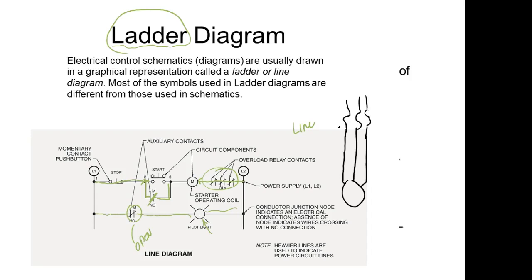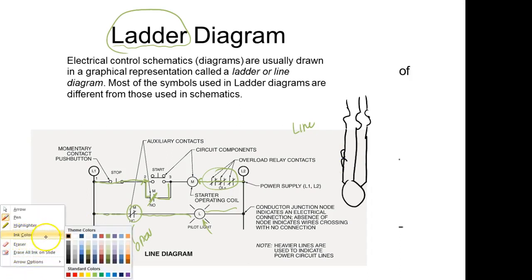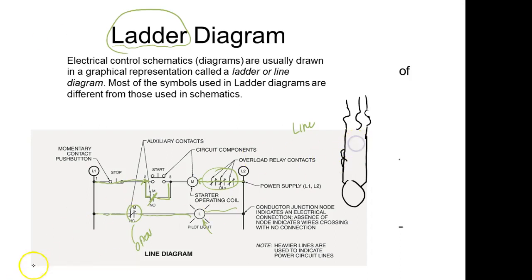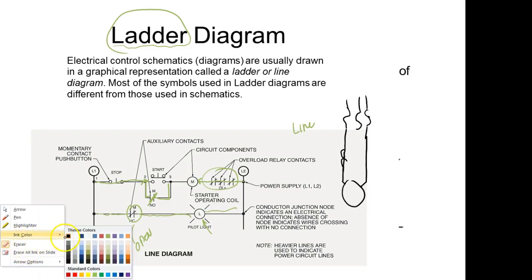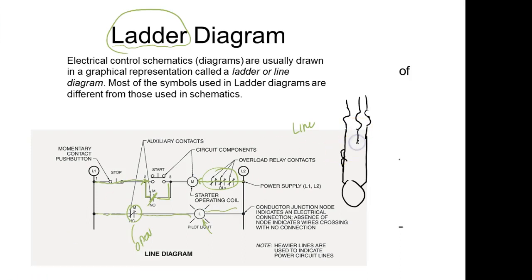So what that means, we need to come up with some method where we can sense when the motor draws more over current over a certain amount of time, right? You understand? So this is what we call overloads. And these are symbols for overload sensors. So what we do is we put overload sensors out in series with the motor. So everything that goes through the motor has to go through the sensor.